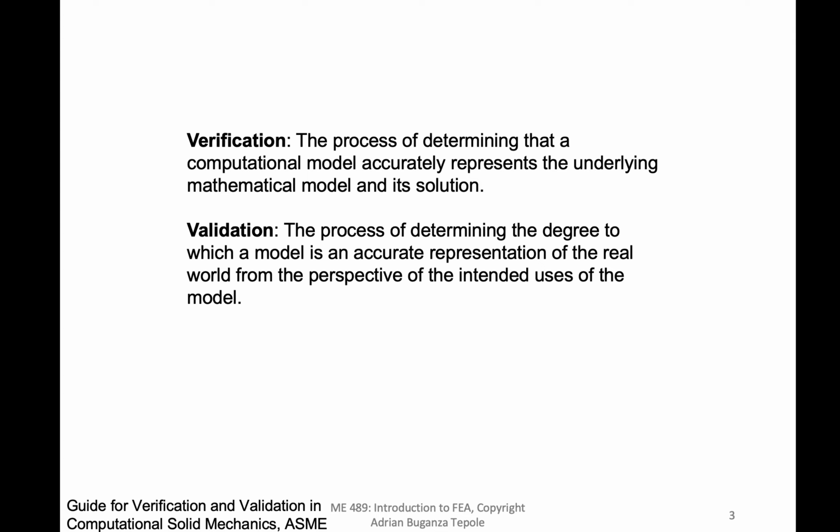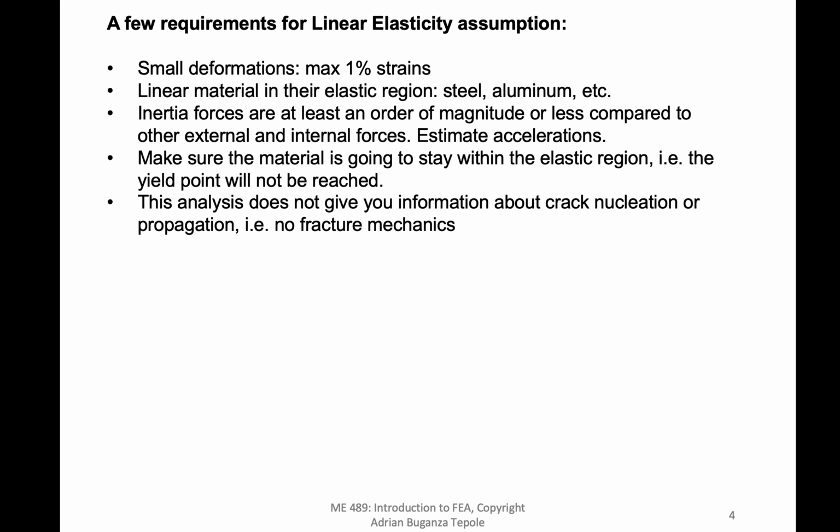And that second point is the first one that I want to tackle here, which is when we say we are solving a linear elasticity problem where we want to analyze the stress in a part and we're using the linear elasticity assumption, what do we mean? So when is this going to work and actually represent the physical world? One aspect of it is we need small deformations, a maximum of around 1% strain.